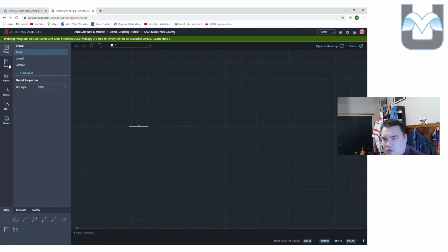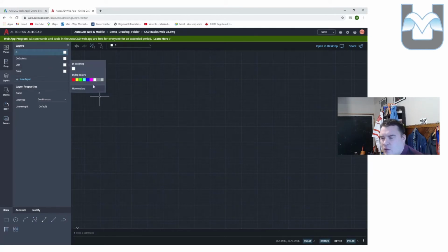We're going to set up what we usually set up here, where we go down to our properties, turn our dimensions to standard, we turn our text style to standard, and our multi-leaders to standard. I'm going to go to layers, make 2 new layers. Again, the draw and the dimensioning layers are the ones that we're going to be working with this fine day. I like those colors. Problem is solved. We're going to go to our drawing layer.